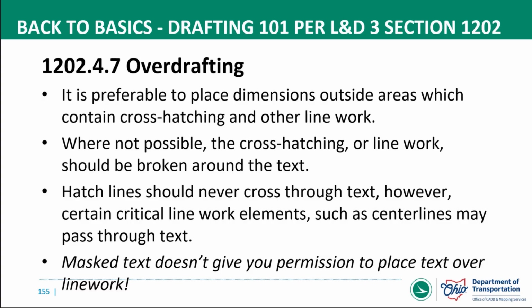So overdrafting, this is where you've got just text and dimensions overlapping other elements on your drawing, other lines, other text, other leader lines even. So it's obviously preferable to place dimensions outside the area in which they contain cross-hatching or other line work. Cross-hatching or line work should be broken out around text. That is usually pretty easy with masked text. I guess that's one advantage to that.